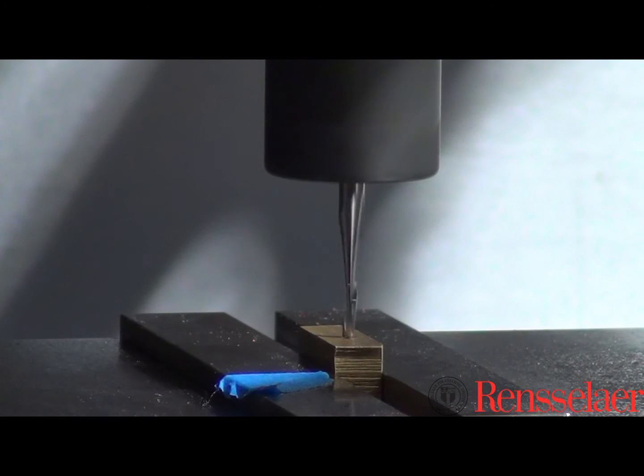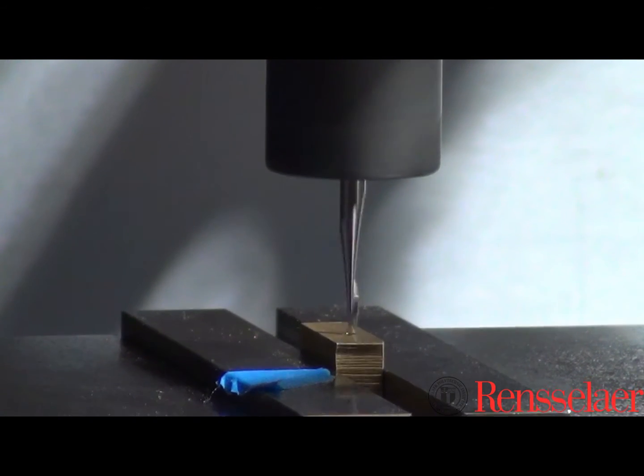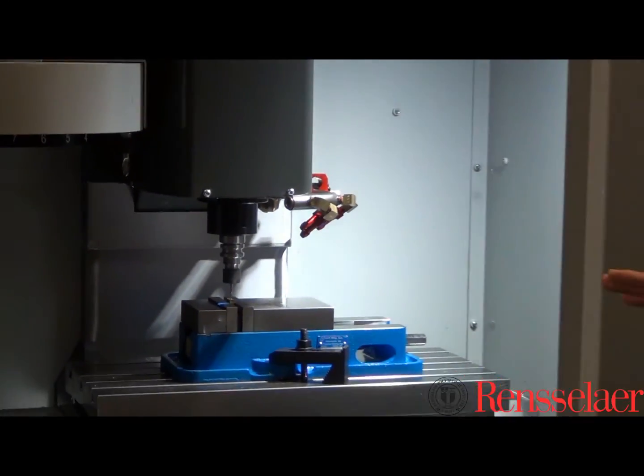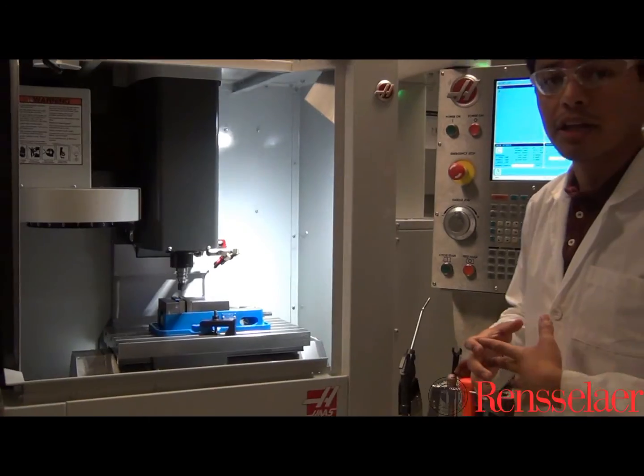You can see, we started making, we did the first chip. We made the first chip. That to us indicates that the tool just grazed the workpiece, and from there, that's an indicator for us to set the tool length offset.